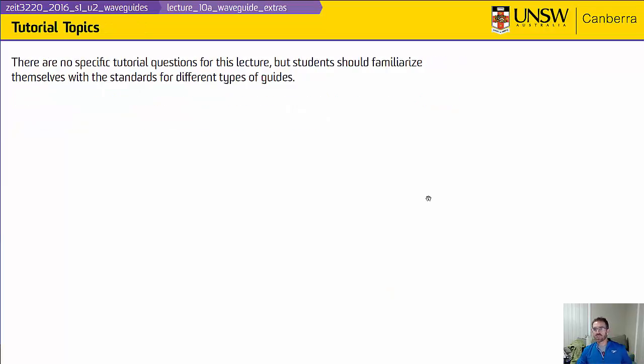So there's no specific tutorial topics associated with this lecture. However, the practical details here are the ones that could come of use to you. If you know you have to work in a particular frequency range, you can go to your textbook, Pozar, and look up what waveguide you want to be getting. There are many different manufacturers that will make waveguide to those specifications. You can find those waveguides and look at their properties, and depending on what material they're made out of, you can look at their loss and be able to decide what's going to work for your particular application.